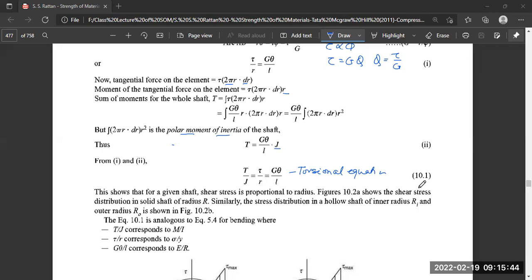There are two types of forces, rectilinear forces and torsional forces. What is rectilinear? This is acting on a straight line. The force may be tensile, compressive, or bending, but it is acting on a straight line. And it is single. It is not a number of forces acting at the same time. How is it acting? This rectilinear force acts along the longitudinal axis of, say, a prismatic bar of round cross section of any length.